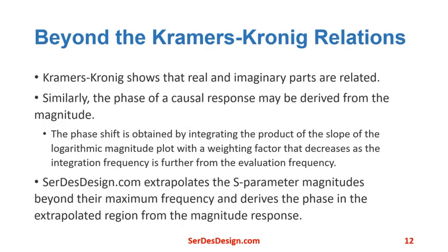Beyond the Kramers-Kronig relations, SerDesDesign.com relies not only on the Kramers-Kronig relations, but also on an extension to these relations beyond the S-parameter's maximum frequency. The Kramers-Kronig relation shows that the real and imaginary parts of a causal response are related. Similarly, under certain conditions, the magnitude and phase of a causal response are related.